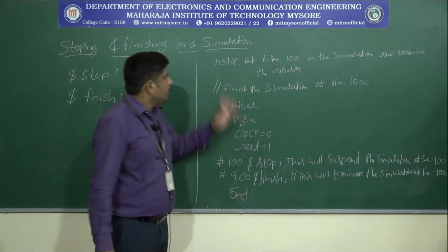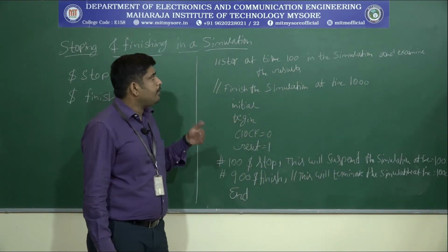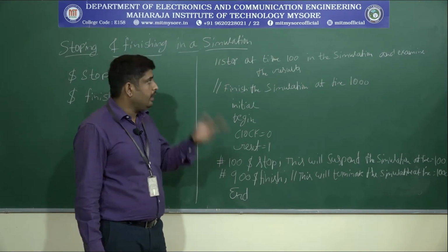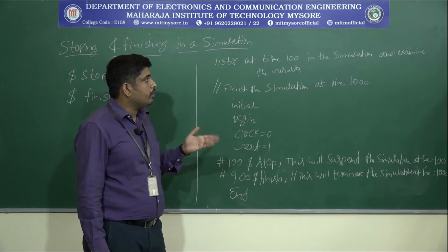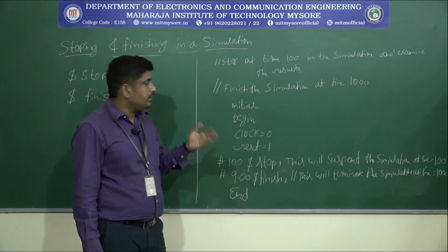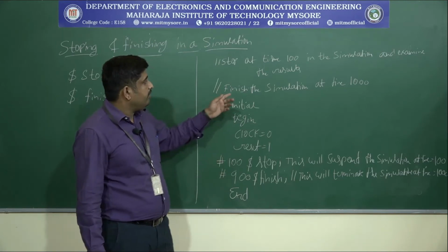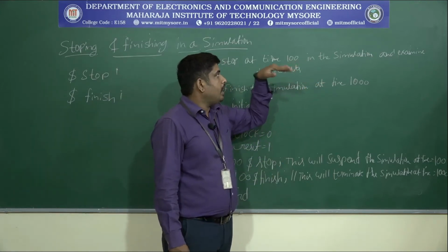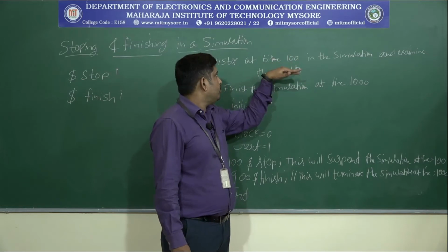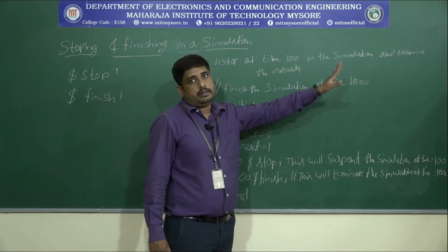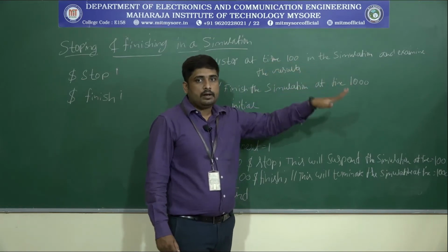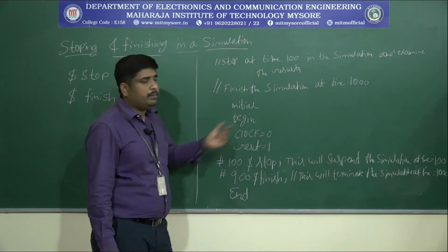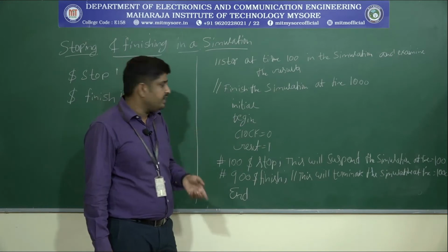Here our agenda is: stop at time 100 in simulation time and examine the result. So we want to stop the program and examine the results. That is our aim. Then finish the simulation at time 1000. So first at 100 nanoseconds we want to stop the program, then at 1000 nanoseconds we want to terminate the program. So here, initial begin is the keyword for Verilog HDL.